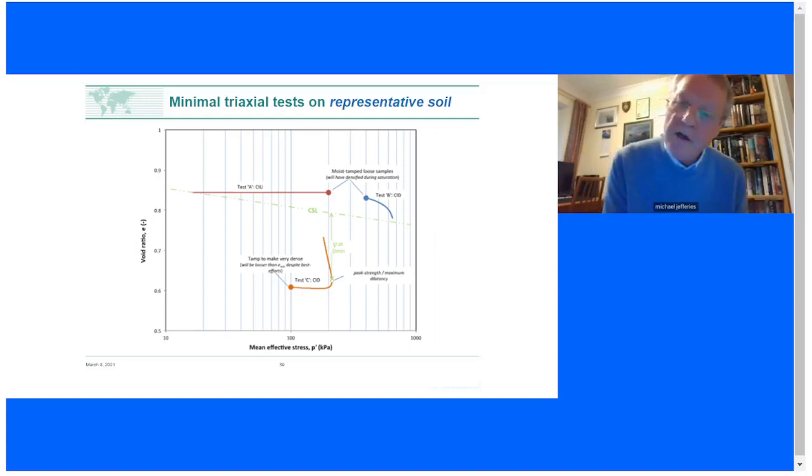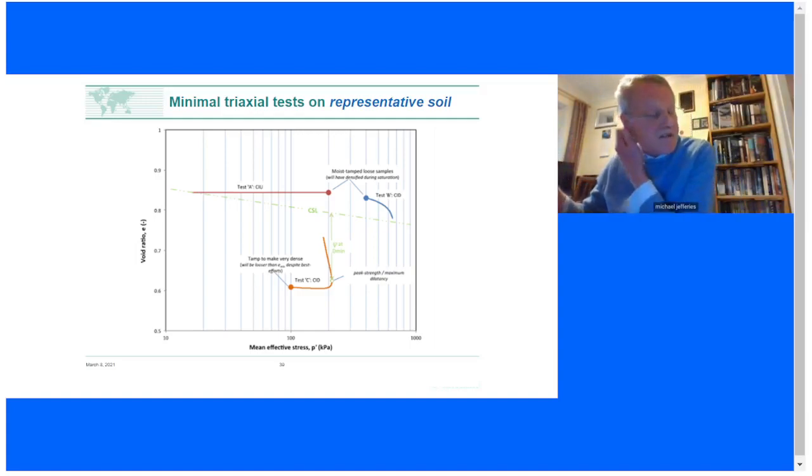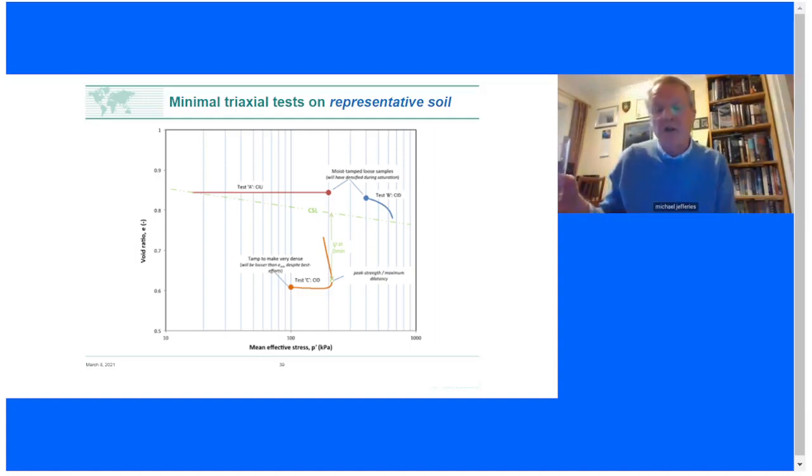And we're going to infer or determine our properties by comparing test 1 with test 2 with test 3. If we use a different soil in each of the different tests, we'll get nonsense. So what you have to do is take your sample, and you then have to slice it and dice it into a number of representative samples, each of which is going to be identical, and you'll test those identical samples.